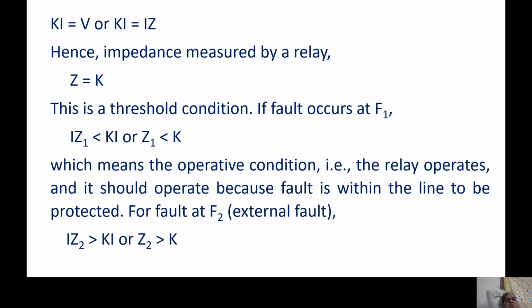See, very important point. It covers first, second, third and fourth quadrant, every quadrant. And I want to measure the impedance only in first quadrant. So from that angle this characteristic is not useful. But this is the basis of distance relay.